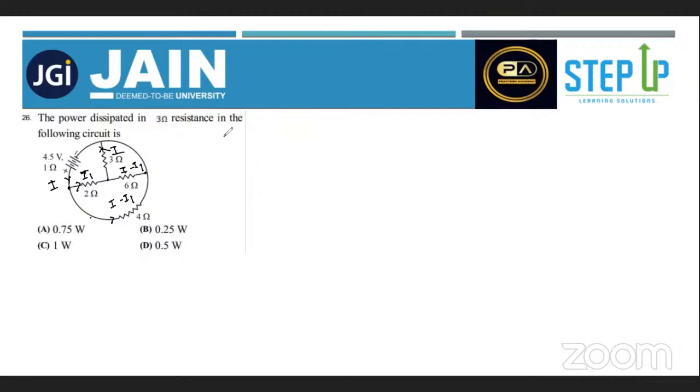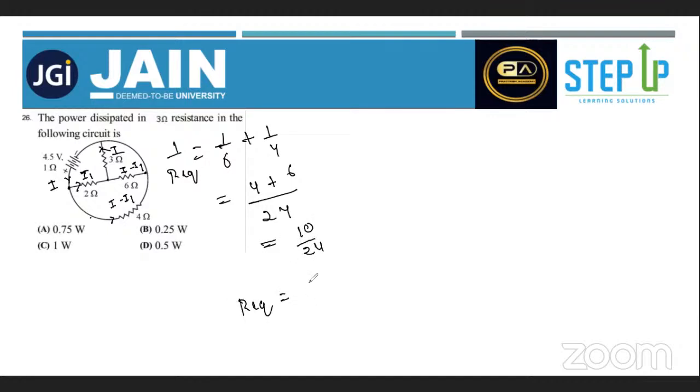If I'm writing 1 by 6 plus 1 by 4, what should R equivalent be? So this will become 4 plus 6 over 24. I'm getting it as 10 by 24. Basically R equivalent will become 24 upon 10, which is nothing but 12 upon 5.